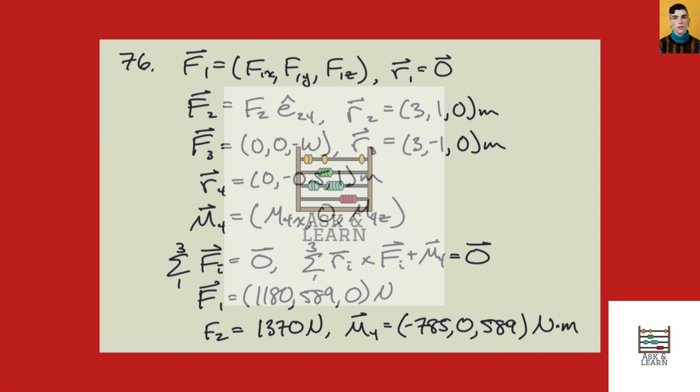Now the tension in the cable is 1,370 newtons. The weight here, for reference, is given in the book, is about 400 newtons. So what you can see is that this load, because the cable is at an angle, is actually much greater than the weight of the thing that's hanging from this. And also this force is much greater because a lot of this force has its component in the x direction. So it needs to be offset by that.